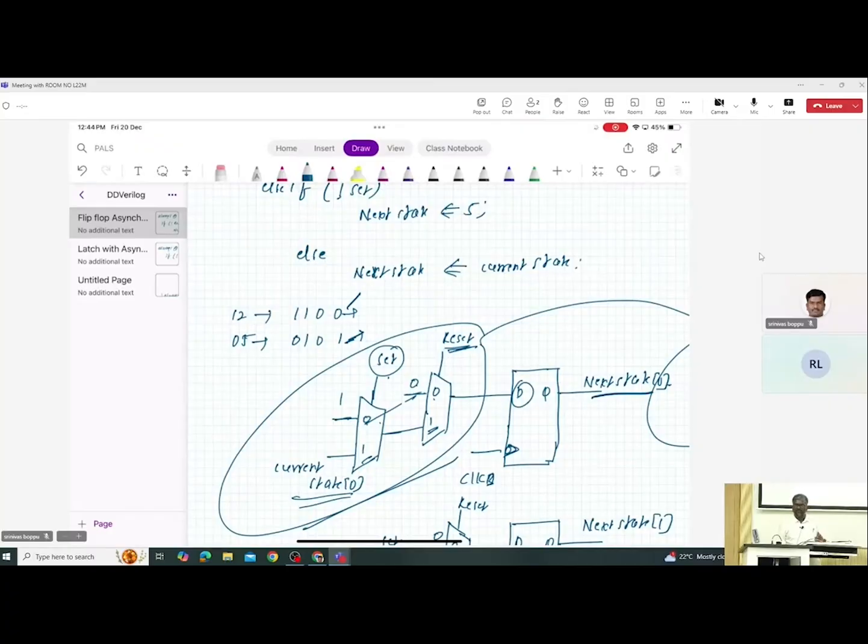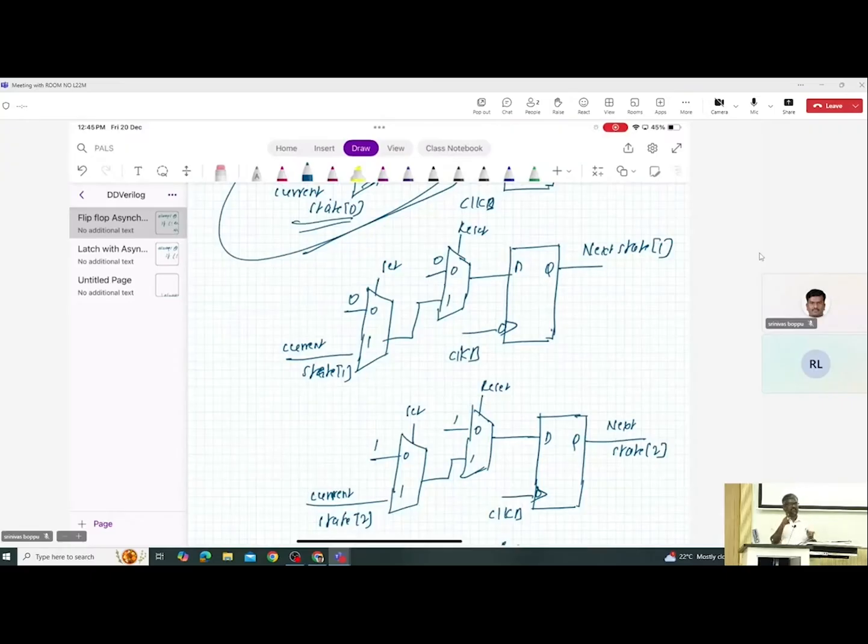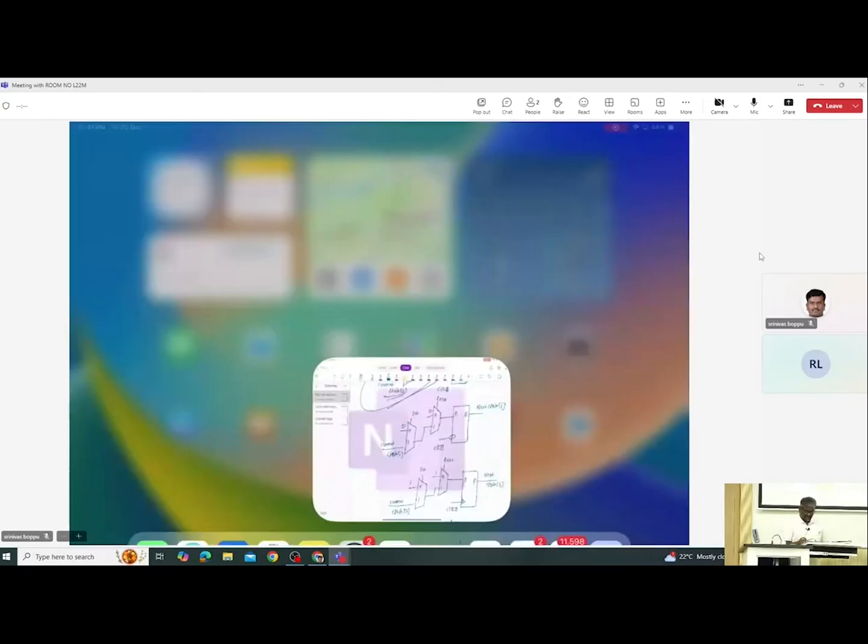So the difference is that earlier we were directing the logic to the preset pin and a clear pin, or the PD pin and a CD pin according to the book. The reason is that they are asynchronous and we have a flip flop in the library which does that. But here it is a synchronous flip flop and we do not have a flip flop with synchronous pins. Now the D pin is the only one synchronous with respect to the clock. So we have to redirect all the reset and set logic to the D pin itself. That is what we did. That is the difference.